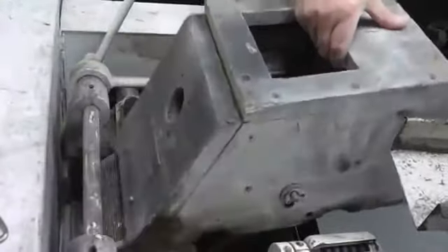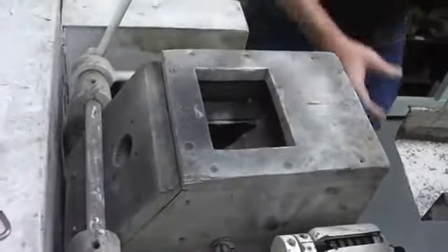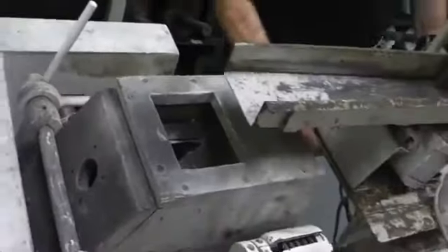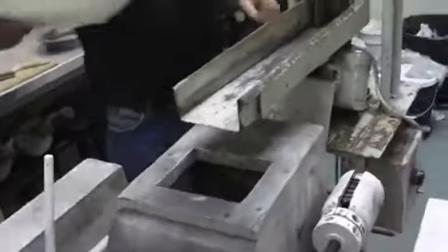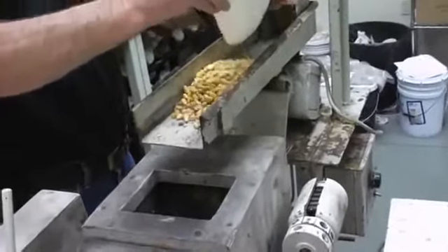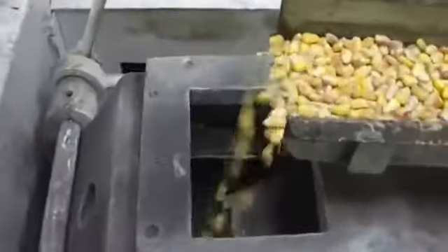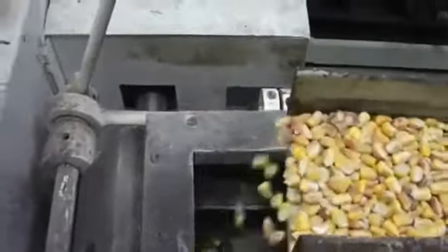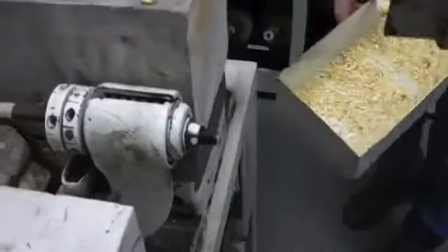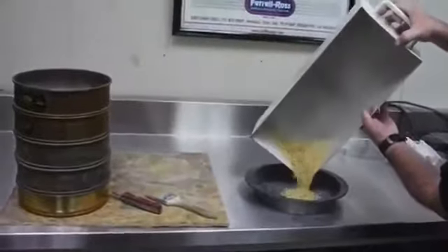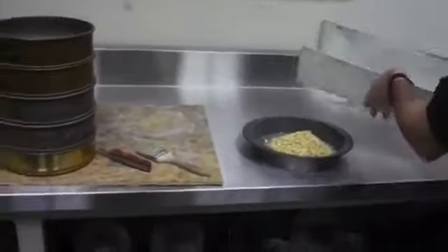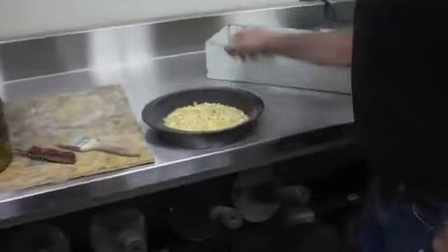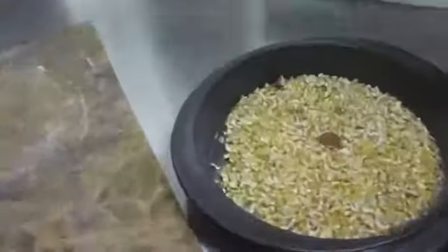Some of the advantages of roller mills are the uniform particle sizes it can produce. In comparison to the hammer mill, about 95% of the product is uniform, as compared to the 70% you would get with a hammer mill. Roller mills also have lower energy costs than a hammer mill. Some of the disadvantages would be the expenses involved with recorrugating a roll and the difficulty of removing the rolls from the mill and transporting them to get recorrugated. Another disadvantage is that the roller mills have trouble reaching the small particle sizes that a hammer mill achieves without rerunning the product multiple times.